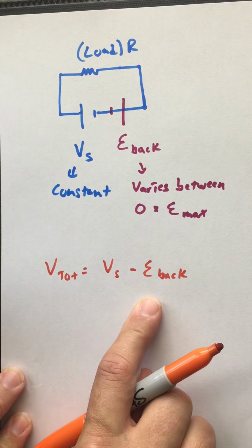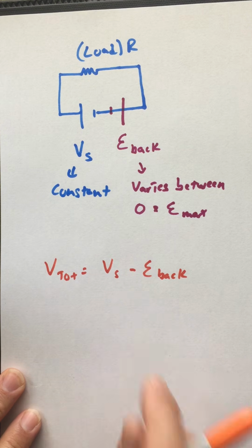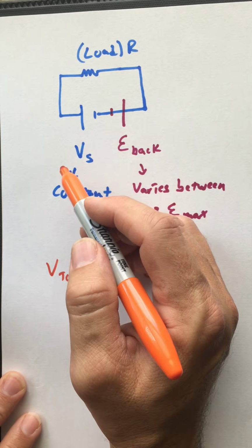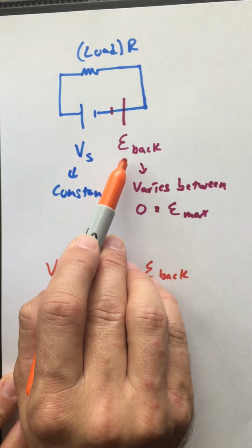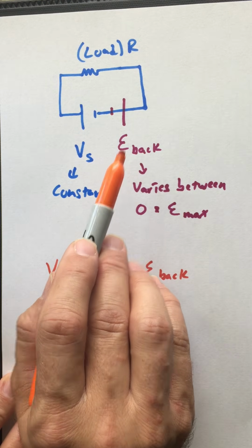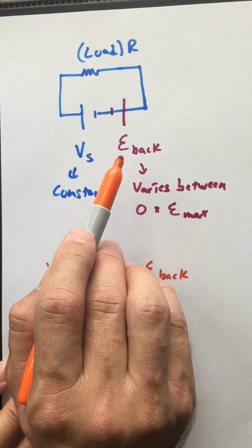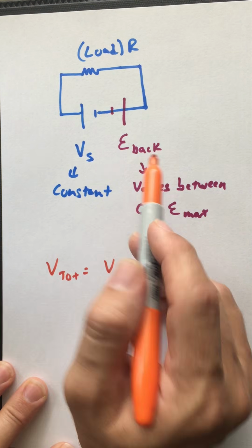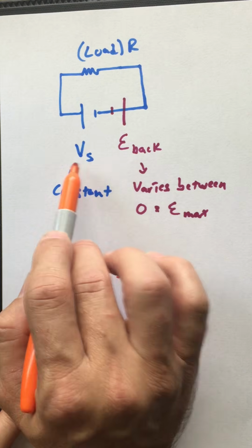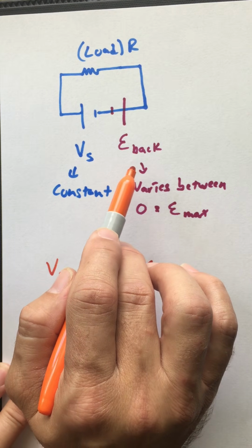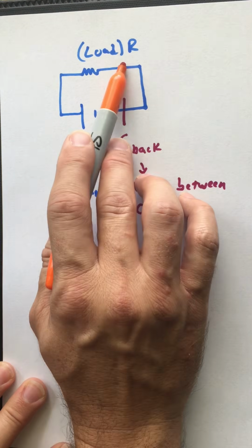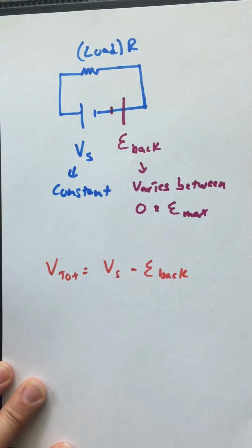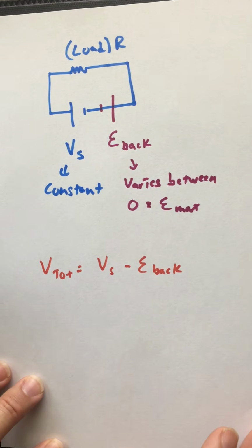Typical way these problems are asked is they tell you either the resistance or the initial current that flows the nanosecond that you close the circuit before the back EMF has had time to ramp up. We'll do the first way. We'll say that we know the current that flows right after I close the circuit. That is before this thing has had a time to rotate. And let's ask ourselves, what is the resistance then that is in this circuit?